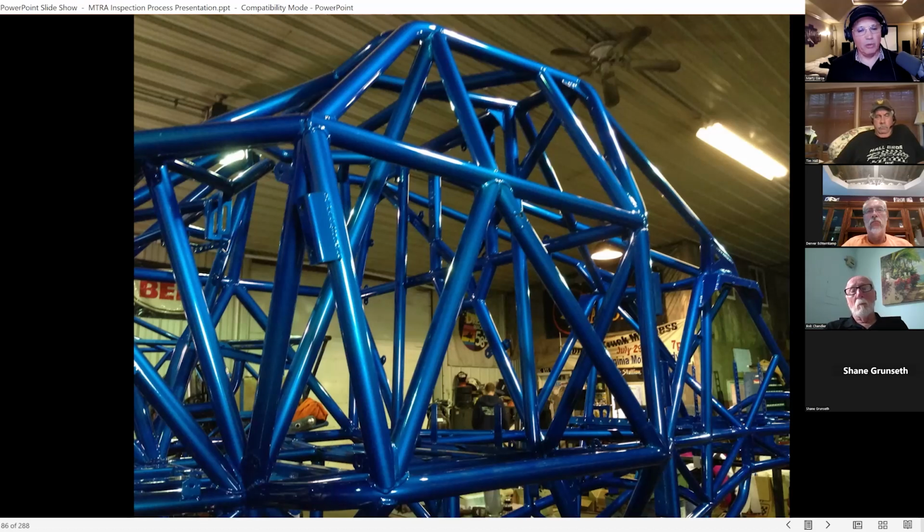We have even expressed concerns about trucks that have only one area of ingress and egress, because some trucks are designed in such a way that the driver can't get out through the side or through the windshield. They can only go out through the bottom. Well, very often that's the fire source. In other words, the fire source is more often than not the transmission. So a lot of times the fire is coming from below. They need to escape through the top somewhere.